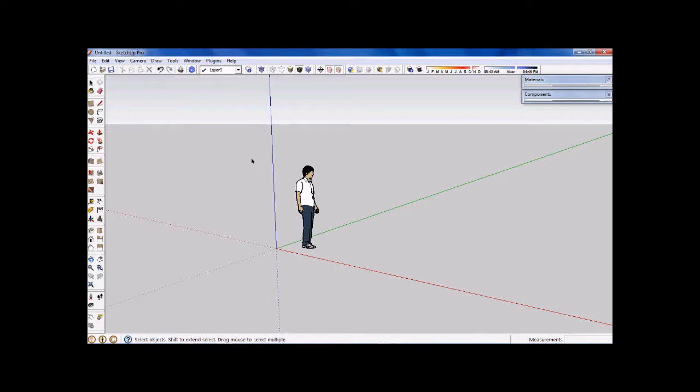I want to set out some construction lines at the moment, and I'm going to use layer 0, the one that is set up automatically by SketchUp. I'm going to use layer 0 for all of my construction type things that aren't going to form part of the final building, but I still need to create them along the way as construction objects. If you'd like to think about this in construction terms of a builder building a building, this could be where all the string lines are set out to line up all the walls with.